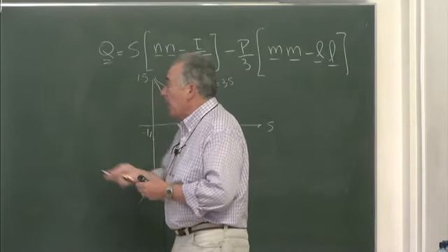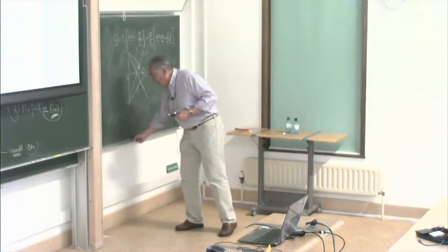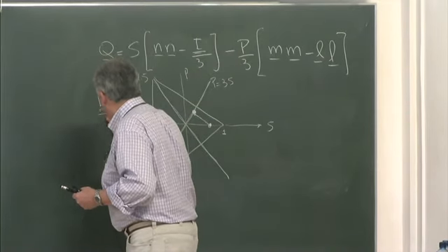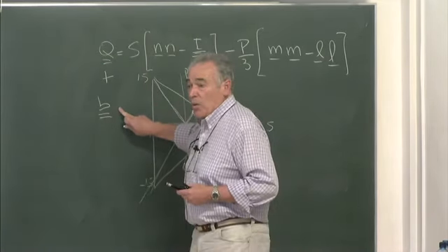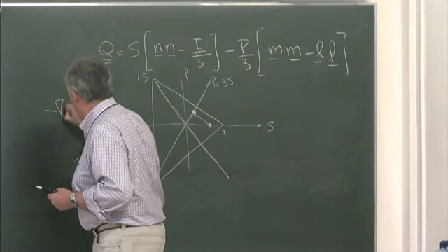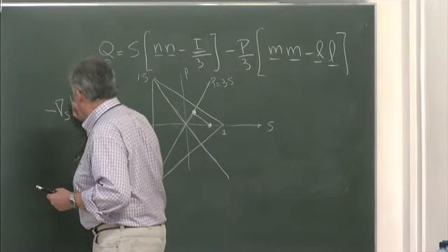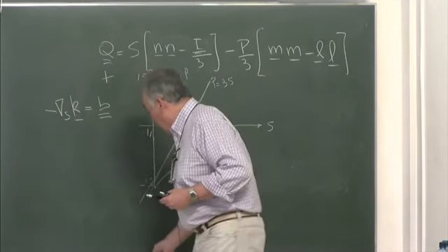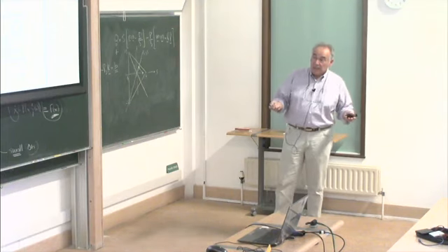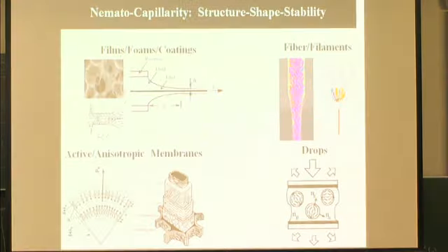Now you have a membrane. The membrane has resistance to bending and torsion. So you have to augment your description with a curvature tensor, which is just minus the surface gradient of the unit normal. That is the way to handle these important new problems of anisotropic membranes.